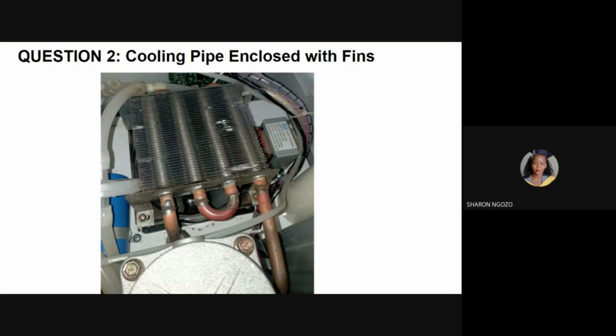One thing you also have to note is that if the heat goes to the sieve beds, then the purity will be affected. The concentrator's purity will be affected. You will not be getting good purity. Thank you, Mai.